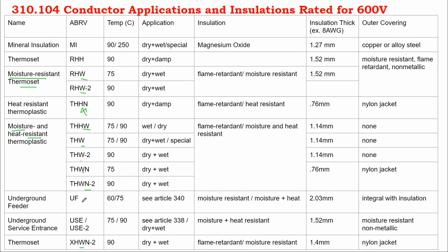Now you could have other wet rated cables that are more industry specific, but these are just general acronyms. You go to Home Depot and you see THHN cable, which is just a single conductor, high temperature cable that's not for a wet environment. It's a common single conductor cable that's put into homes.